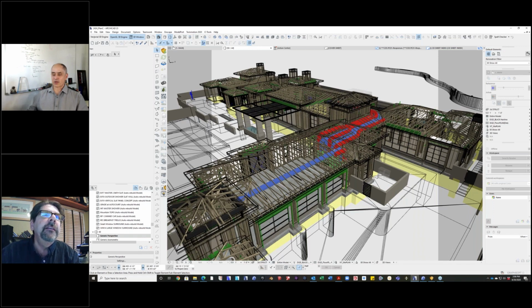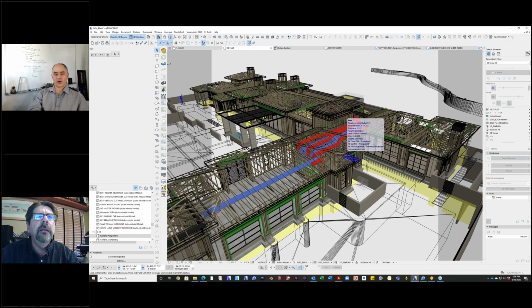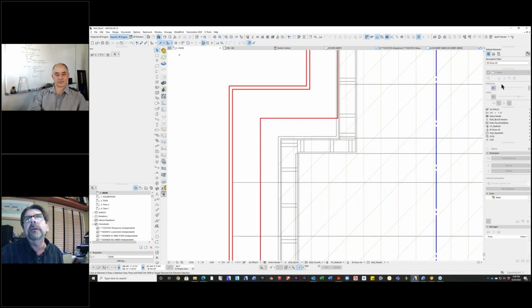How does that coordinate with composite structures? I'm not sure if he's referring to composites or complex profiles, but basically, how does all your framing coordinate with the volumetric walls in ArchiCAD? Well, that's the semi-automatic part. It doesn't coordinate. It doesn't do anything automatically. I have to stretch them to the right width. I do have wall types that are composites.